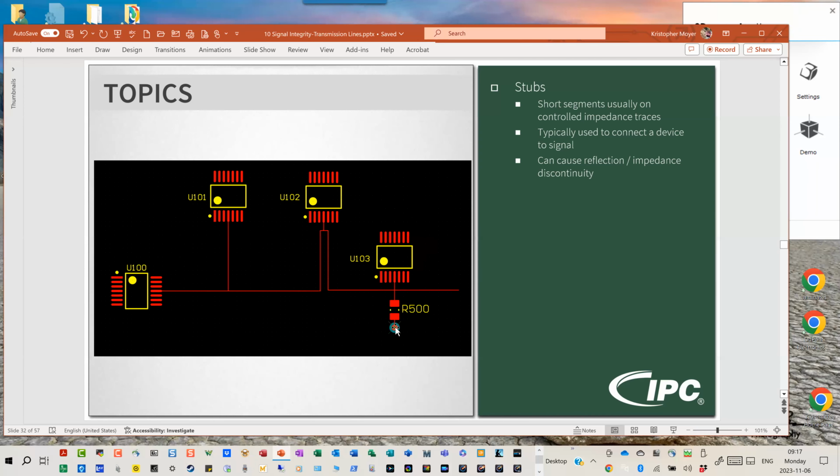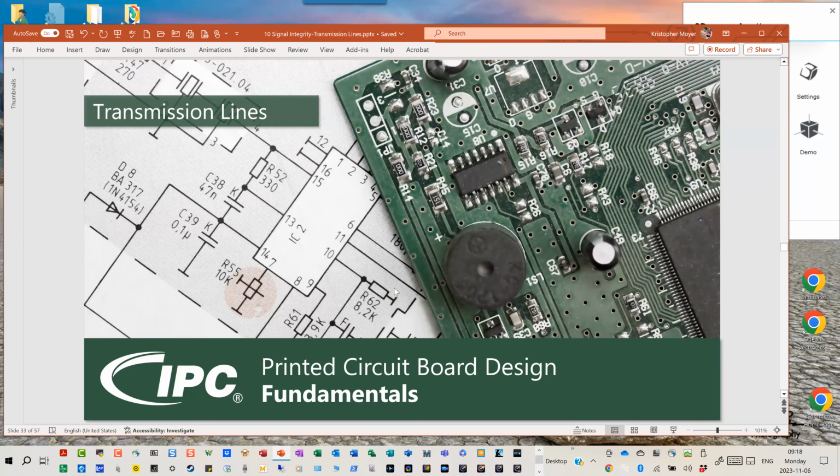We also have to be careful with pull down resistors like this one right here, where we pull down, and this is actually whatever resistance this pull down is plus our transmission line, in parallel to the 50 ohms right here. Now, if this is sufficiently high resistance, it's not a huge problem because our impedance for our transmission lines is typically low, like 50 ohms. So let's assume this is like 1 or 2 kilo ohm kind of thing. I'm not going to see a huge discontinuity right here, but we do have to be careful and calculate what that characteristic impedance change is, and if it's going to be problematic for us.